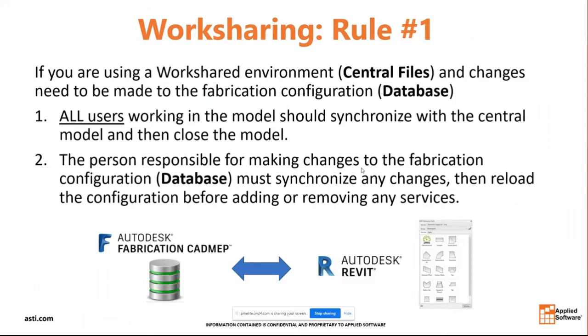In the Revit realm, because work sharing is something new, this central file, local file is a whole new process. It's causing issues. It's hanging up the database. It's locking you out. If you ever try to reload the database or reload the configuration and it's grayed out and won't let you reload, it's because something happened like this and the rules weren't followed.